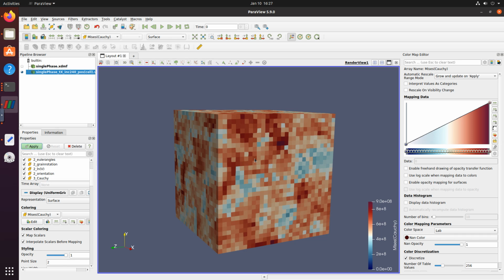So it is always a question, and then there is also a limit on the resolution. Just like mesh dependency, if we refine the mesh size beyond a certain extent, the results also stop changing. They do not change after that at all. And then the question always is, what kind of results are you more interested in? If you're interested in the local results, it is always a good idea to define a better resolved geometry, which has more detailed grains, and the results are locally resolved, and then you will be able to see what is happening inside the material.